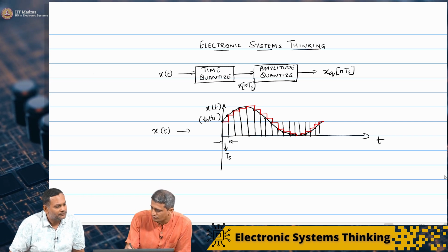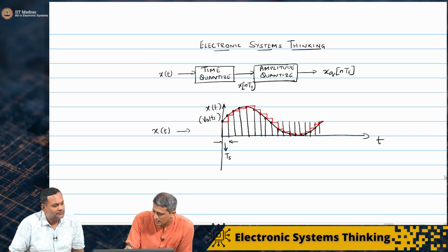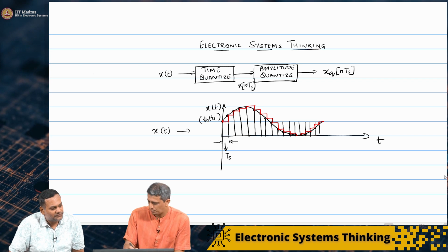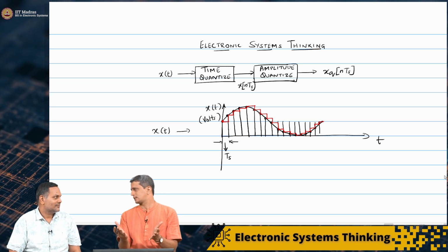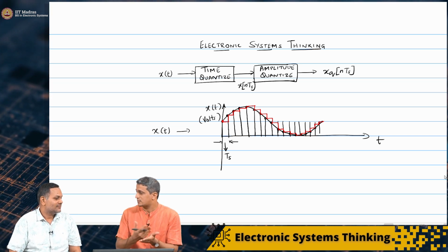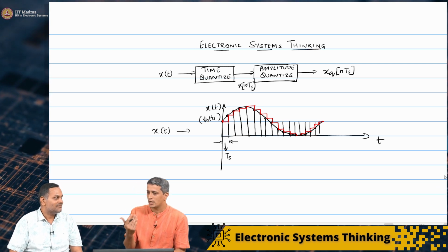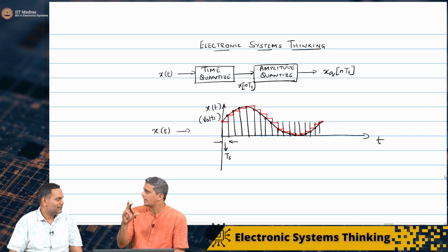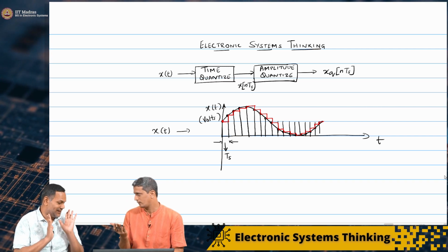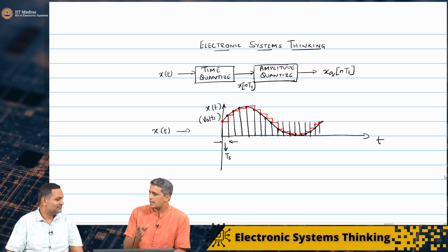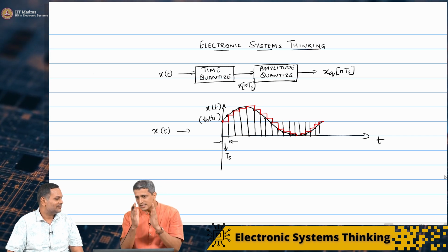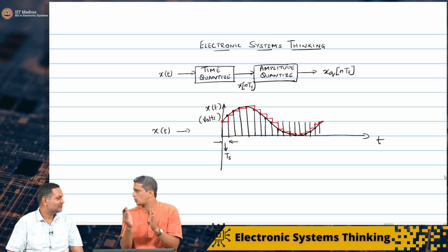So in some sense we take this red dot here, but in Ts we are assuming that the signal is not changing fast enough. This is something we discussed last time. If you have a very fast wiggle there, it means you're not sampling fast enough, and you're losing information. So it's safe to assume that in this sampling instant the voltage does not change.